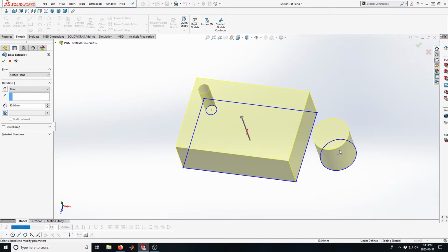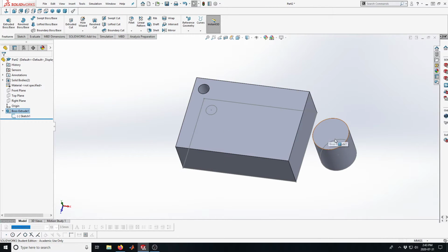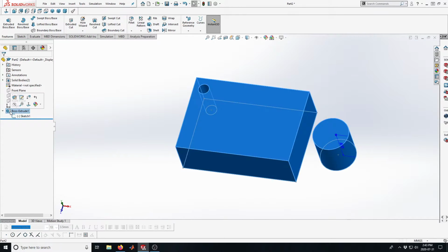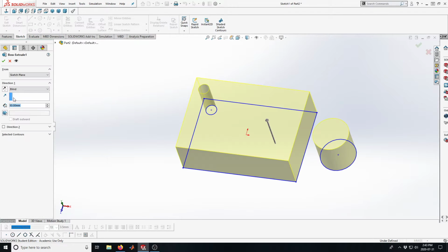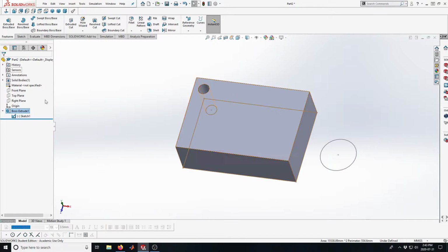Now, it still thought that maybe that was an extrusion, but it didn't quite know what to do with it. And that's not what I intended. In fact, if I go back to Edit and I pick Select Contours, this tool allows me to pick only that contour that I want to extrude, like so.